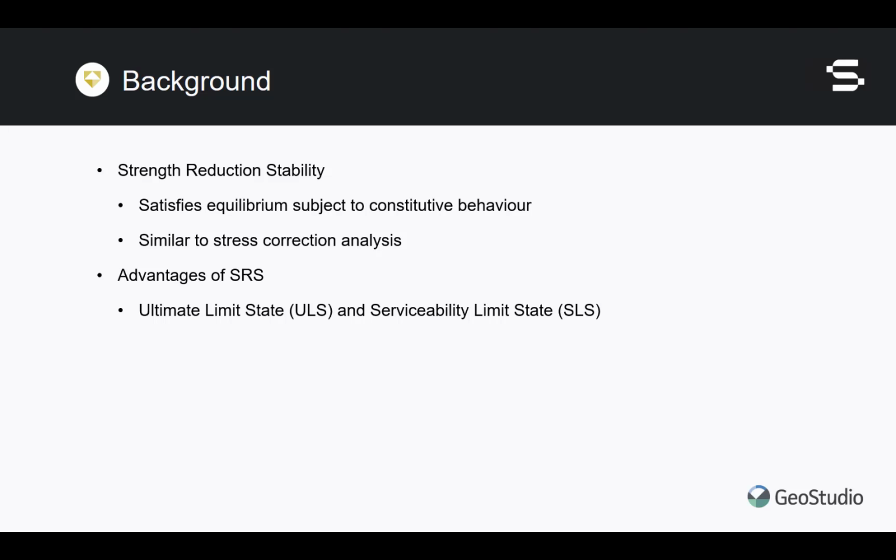In limit state design, the SLS is concerned with ensuring that deformations are tolerable under working load. The ultimate limit state, on the other hand, is concerned with margins of safety against collapse. The soil structure interaction is also considered in this type of analysis, and so we can determine the type of load that occurs within the pile wall.